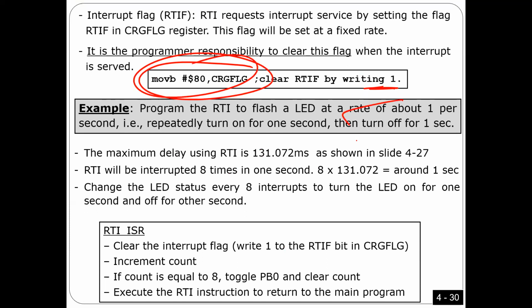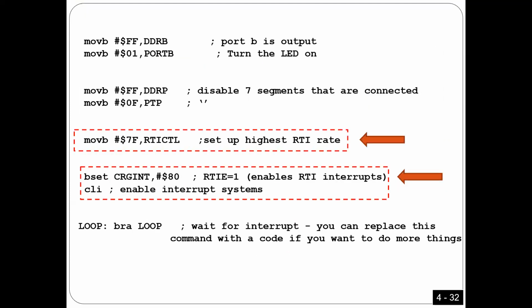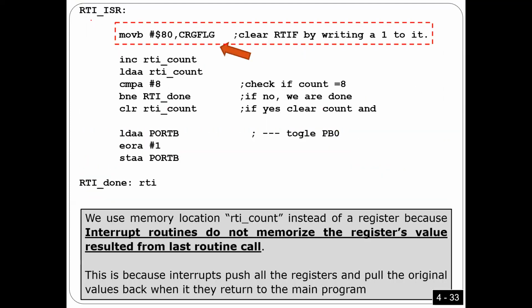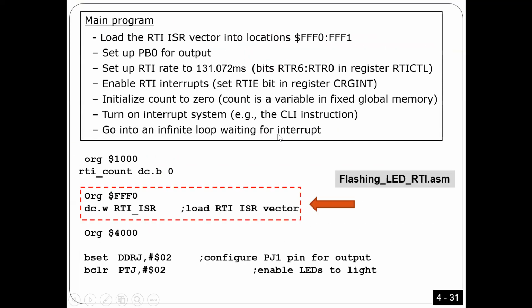Always in the interrupt subroutine. I didn't do this in IRQ. I told you that because this is automatically done in IRQ, but you have to do it in RTI. And every time you just copy paste this one. So as you see here, for example, this is the interrupt subroutine for RTI. I have to put this one. And for any other interrupt other than IRQ, I have to do the same thing as well. Okay, use this one. I'm going to continue next time.